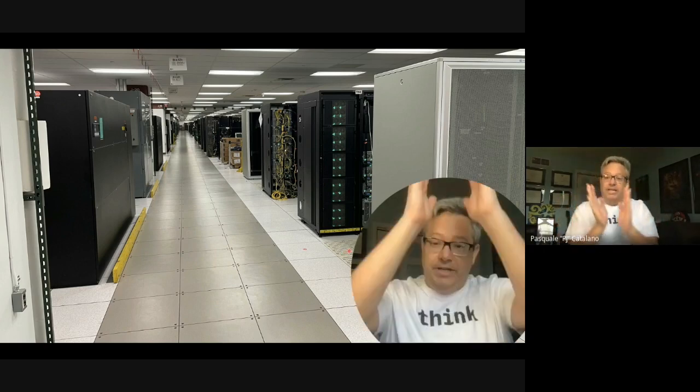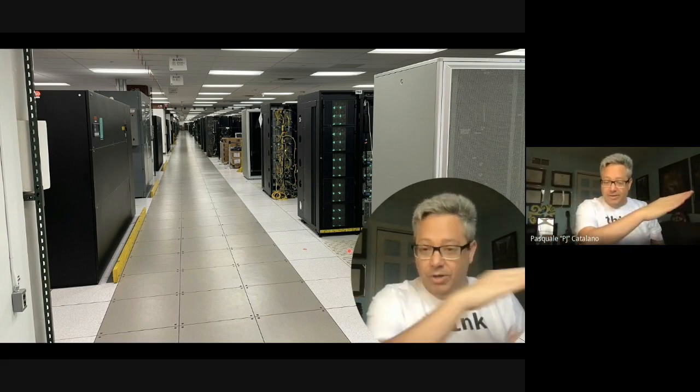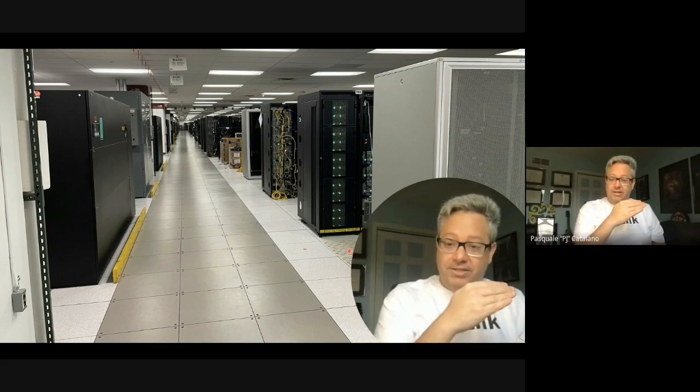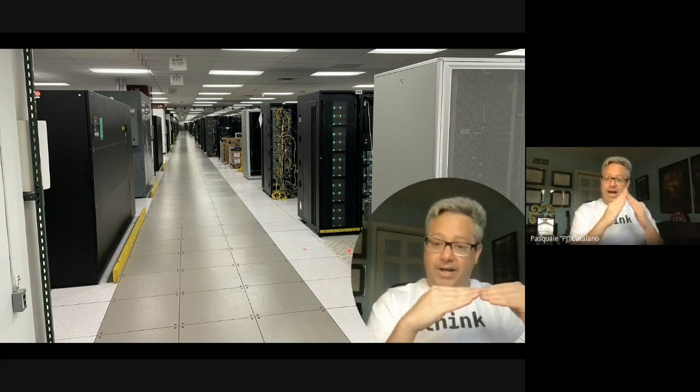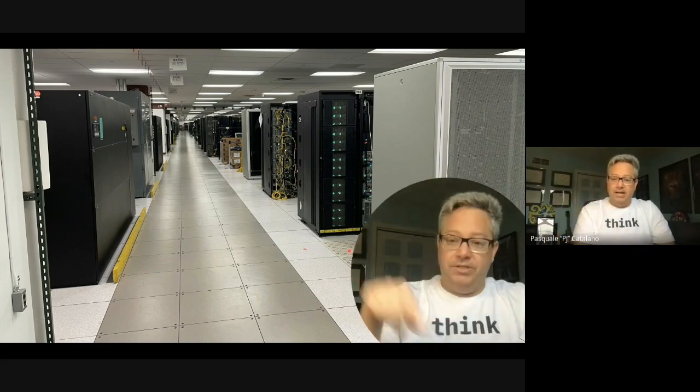The cold air gets sucked into the systems, and then the hot air blows out on the other side. We alternate the systems because we don't want the hot exhaust blowing into the intake of the next row. We actually want hot blowing on hot so that air rises up. And that's what we use to have a convection loop in the data center.